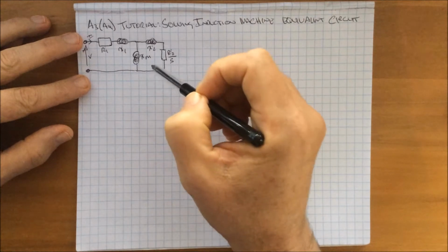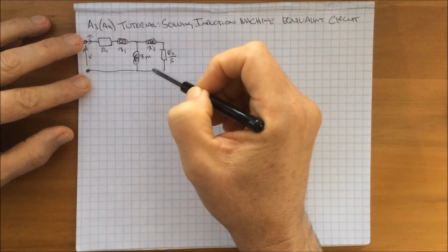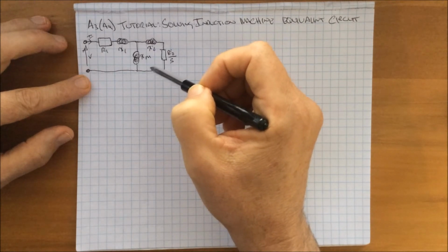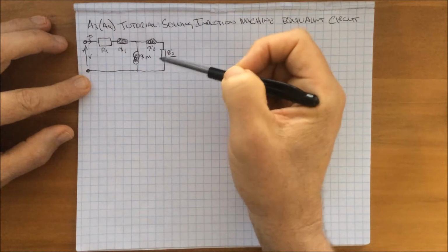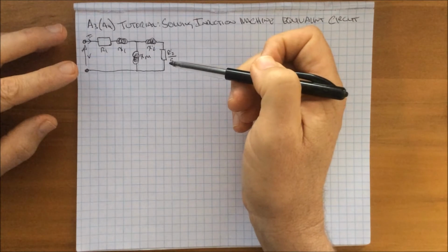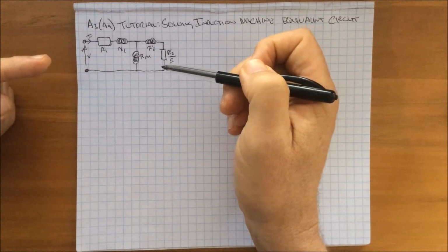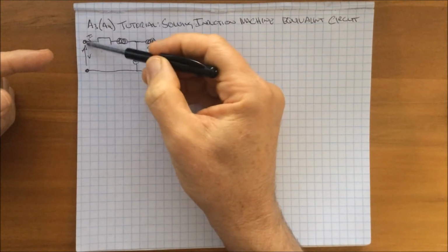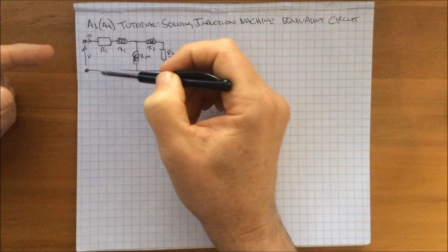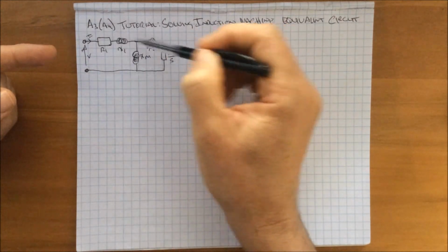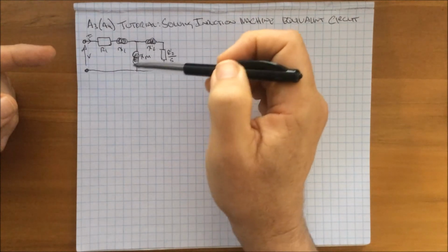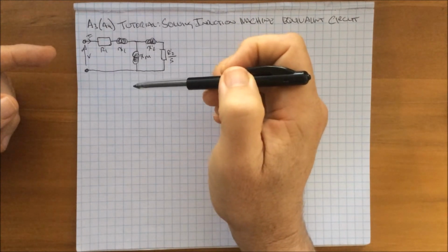So if we alter the conditions of the measurement, we effectively end up with what's almost like a series of unknown values for different conditions, which can be likened to simultaneous equations. And so there are three tests we can do. We can do a DC test, which is where we apply a DC voltage to this terminal and we measure the current going in. And that will give us a DC impedance, and we can use that to start doing some derivation here.